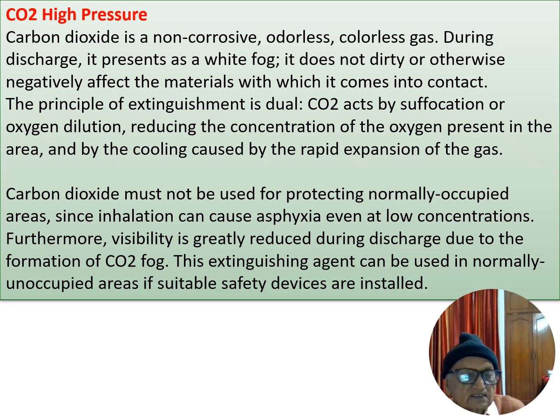Carbon dioxide must not be used for protecting normally occupied areas, since installation can cause asphyxia even at low concentration. Therefore, a signal must be given, voice signal and visual signal both. Furthermore, visibility is greatly reduced during discharge due to formation of CO2 fog. This extinguishing agent can be used in normally unoccupied areas if suitable safety devices are installed.